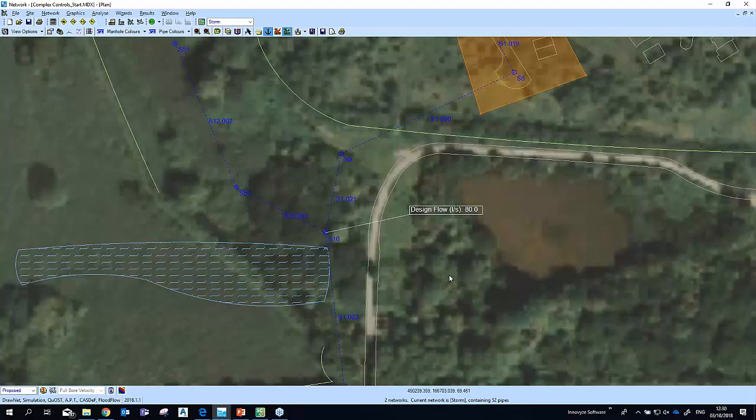And that's because I know that designing this complex flow control could take a while. This could actually be an individual task for somebody to go away and consider. So I've still got some downstream pipes that I need to be able to design. But rather than design based off intensities, I know, because my Q100 year rate is 79.9 litres per second, or near enough 80 litres per second, that my downstream pipe from this flow control chamber is only ever going to have to deal with 80 litres per second of flow. So I can size my downstream pipes using a design flow.